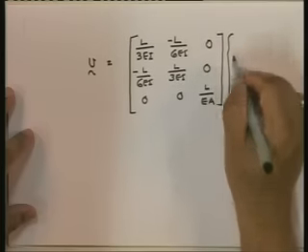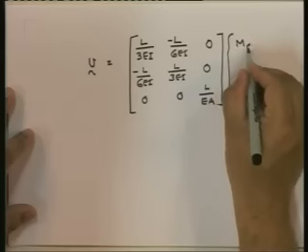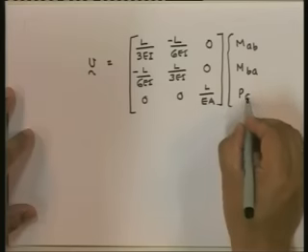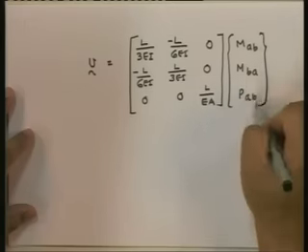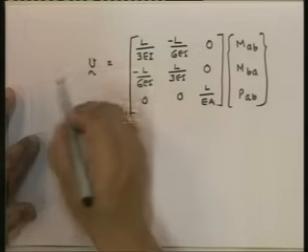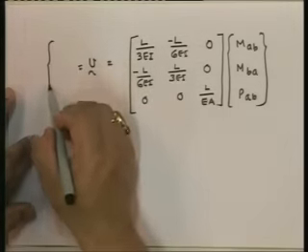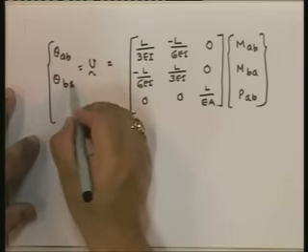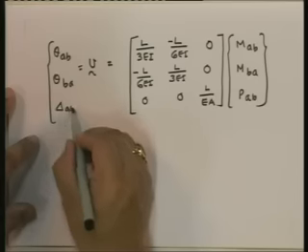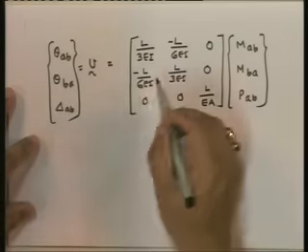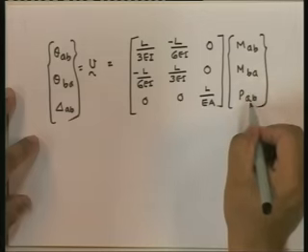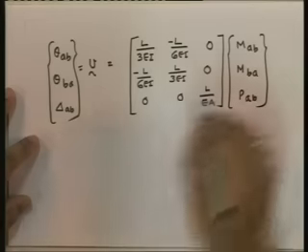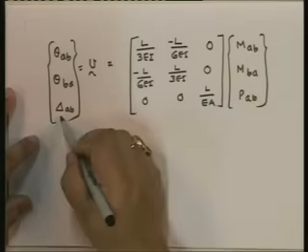This multiplies MAB, MBA, and PAB. This is relatively easy to prove, because for a straight member, PAB does not give rise to theta AB and theta BA, and MAB and MBA do not give rise to any delta.